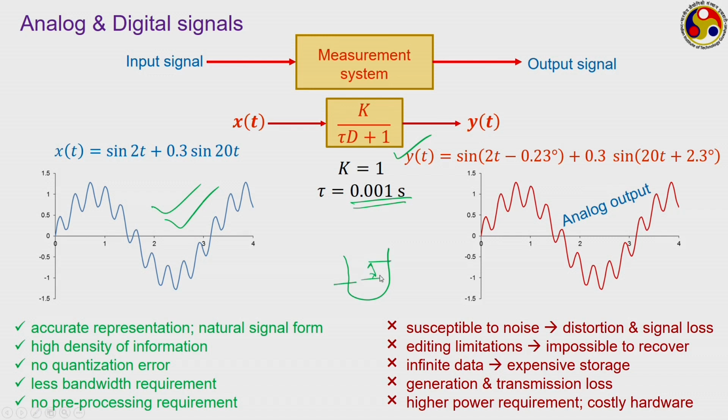Now suppose this particular manometer is mounted on some vehicle. As long as the vehicle is moving with a constant velocity, or it is stationary, then there is no issue. But if this vehicle starts to accelerate, then what will happen? Your mercury manometer will be tilted like this, leading to a different amount of deflection maybe of the mercury column in this, if the vehicle is tilted.